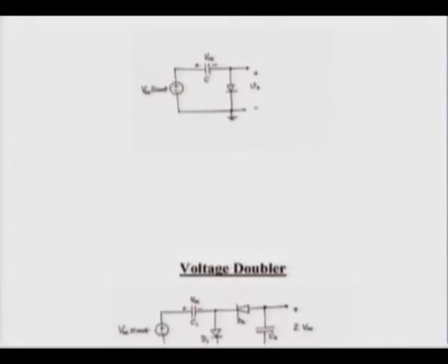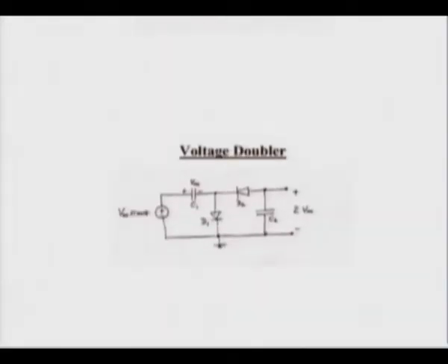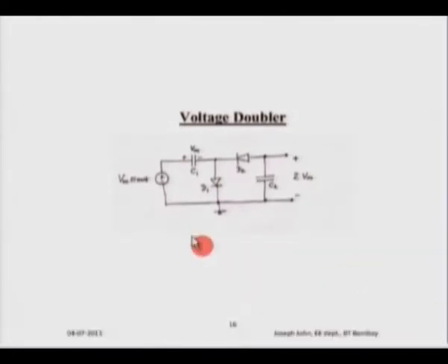Now, these are very useful circuits. These kinds of circuits are very commonly used in what are called DC restoration circuits, where you could restore the DC level. There are other applications such as voltage doublers, where you can use a clamping circuit and a rectifier circuit together.